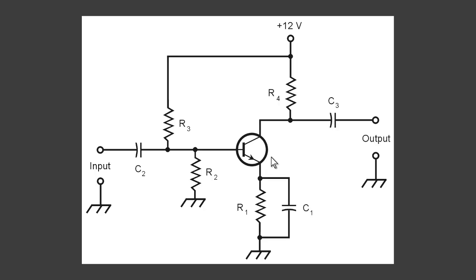When the input signal is too weak to produce collector current during any part of the cycle, we're not going to get anything here, and the dynamic current gain is going to be 0. So that isn't going to work. That's choice B, so we can rule that out. Choice C, in a state of saturation.